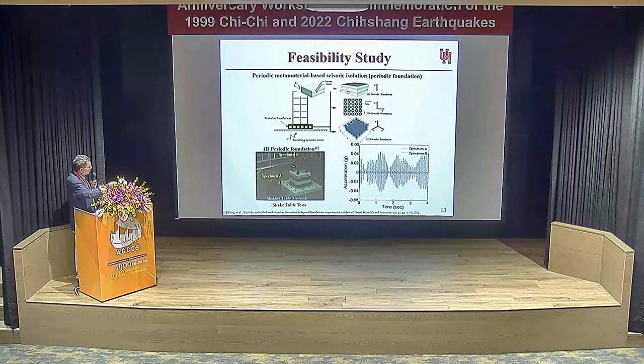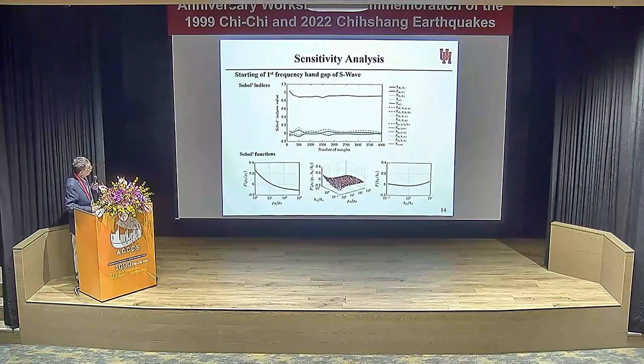As you can see, this is a steel frame sitting on the metamaterial foundation. This is the same steel frame sitting on the shake table. You can see specimen B as this one. The acceleration, the response at the top of the structure, is almost equal to 0. In contrast, for this specimen A, the vibration is much, much higher. And then we are quite confident now.